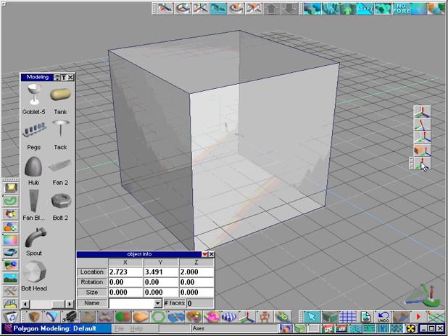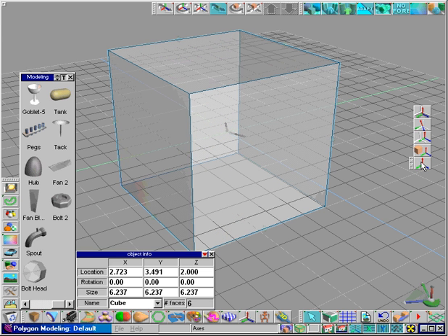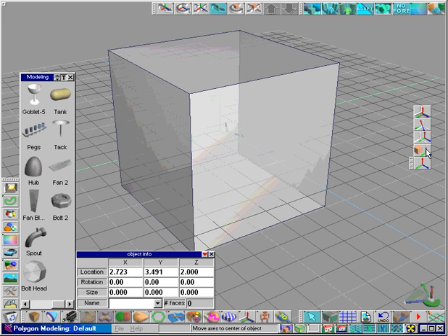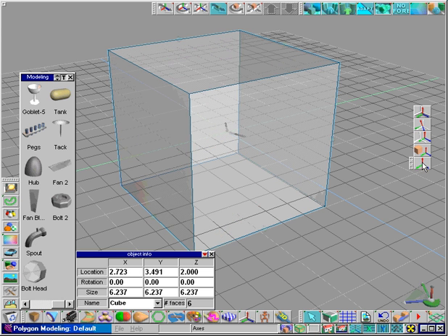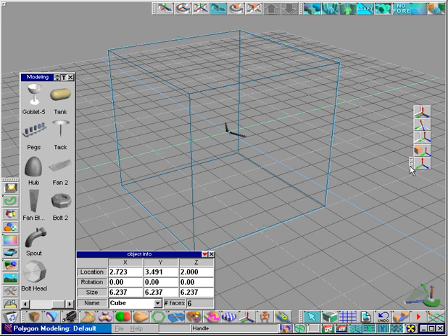The most obvious are the show and hide modes. By simply clicking on the icon, these 2 modes toggle back and forth. Notice that when the axis is visible and active, the selector cage around the object disappears. In wireframe mode, we can see the axis turn on and off. When the axis is active, any translation, rotation, or scaling will affect only the axis and not the object.